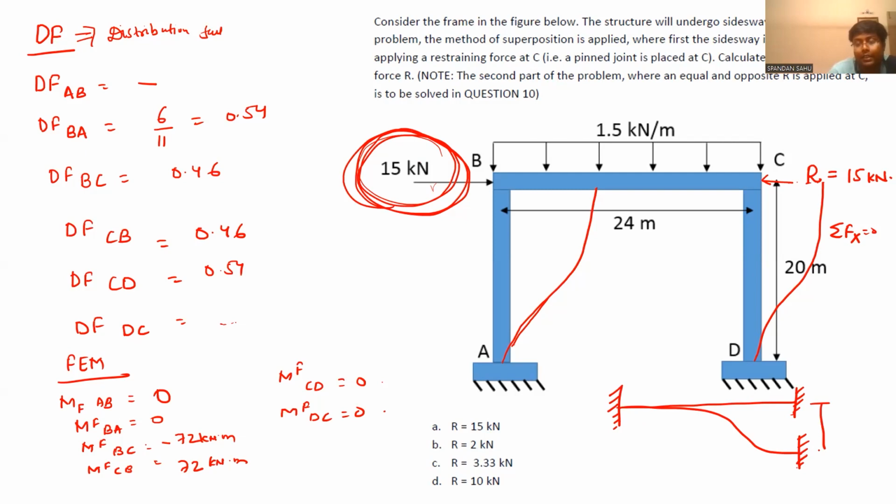In this condition, you are getting two moments whose values are 6EIδ/L². Here also 6EIδ/L². And these two moments are trying to rotate it in an anti-clockwise manner. So reactions will come, but we are not bothered about reactions as of now.